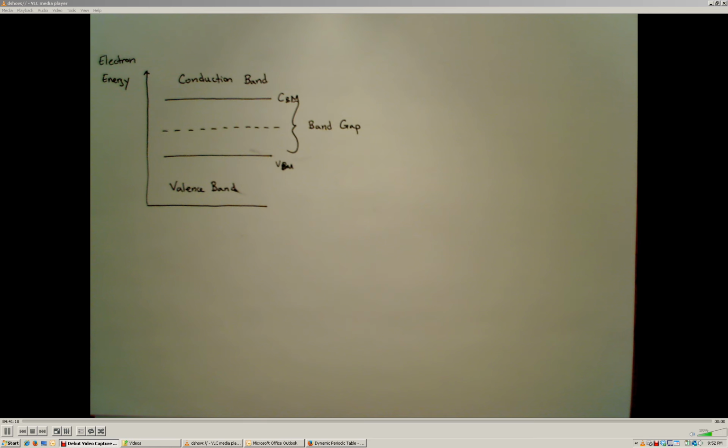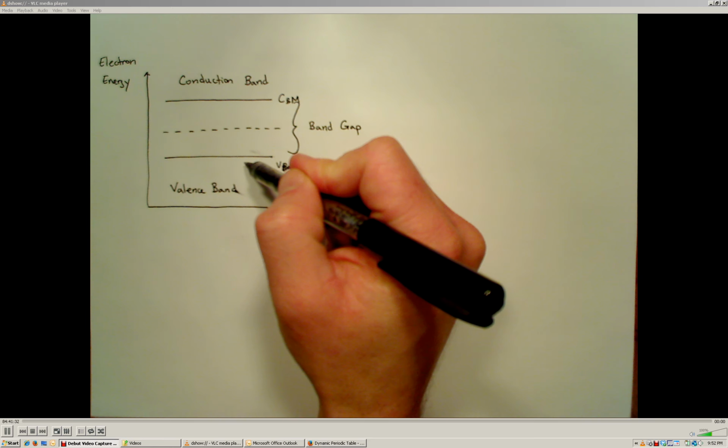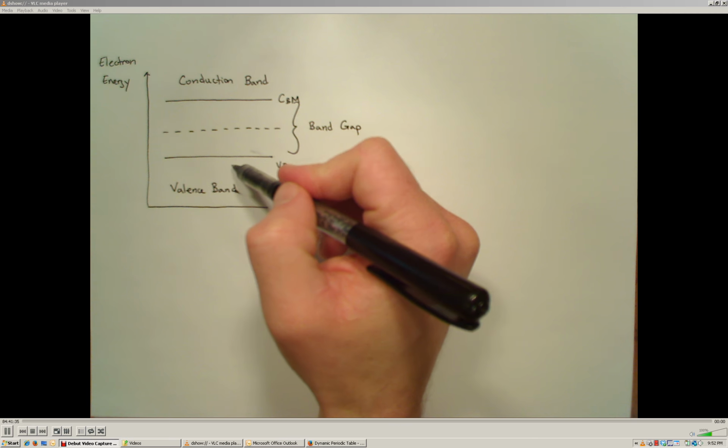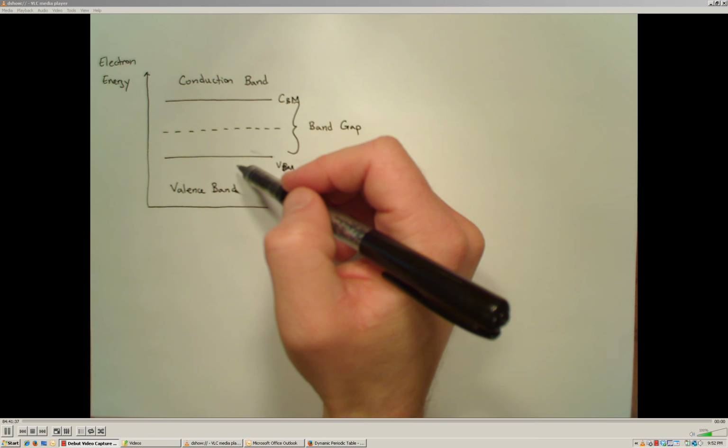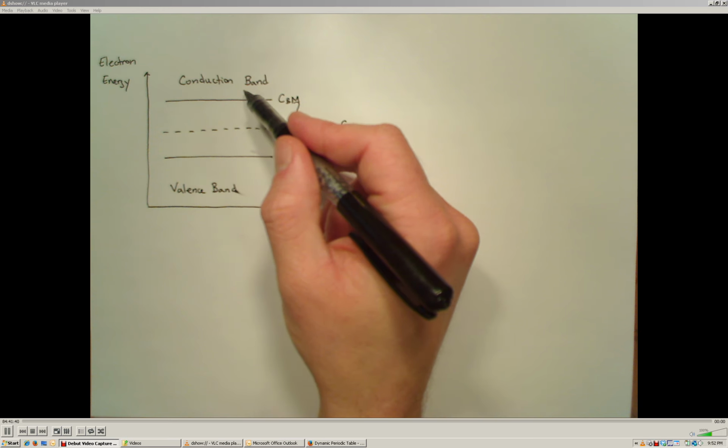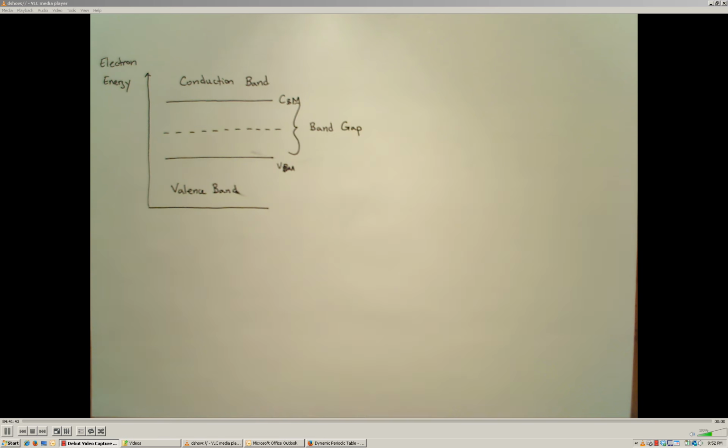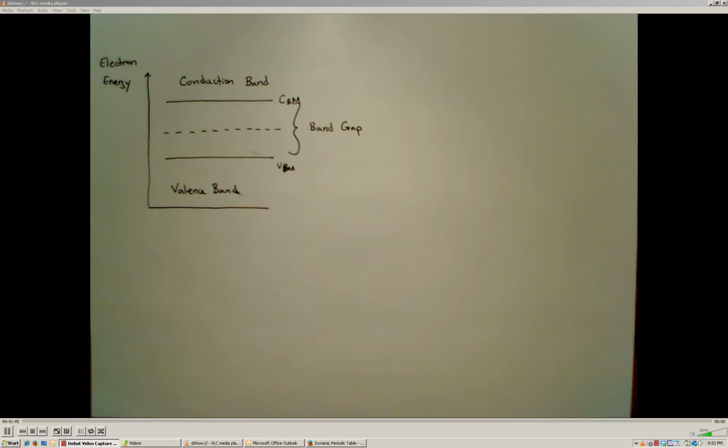So this semiconductor that's comprised of all silicon atoms actually is not very interesting to us, because all it's going to do if we apply a potential across it is act like a resistor. We supply a little bit of electrical energy, and some of the electrons increase their potential energy, and if we provide sufficient energy, they will be able to make it to the conduction band and wander through the material, causing a net current flow. But all that is going to happen is it's going to dissipate energy and act like a resistor. So that's not a very interesting phenomenon.